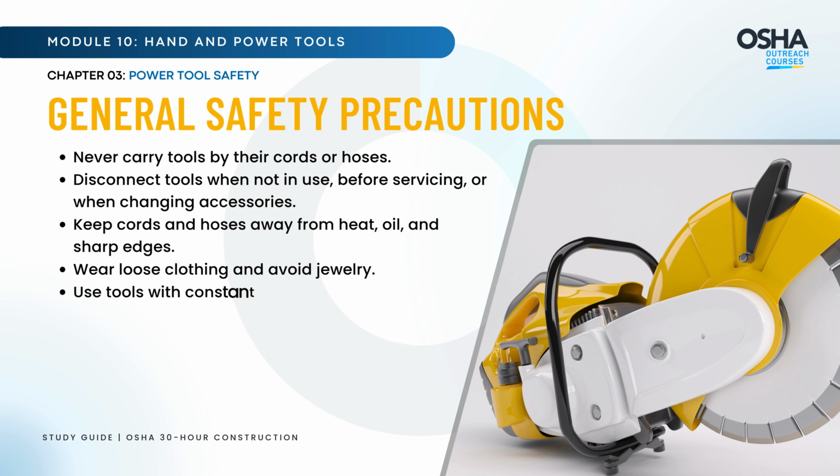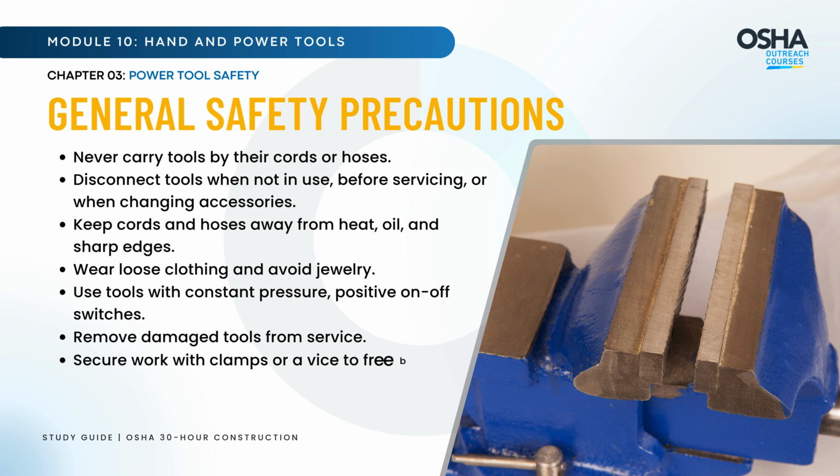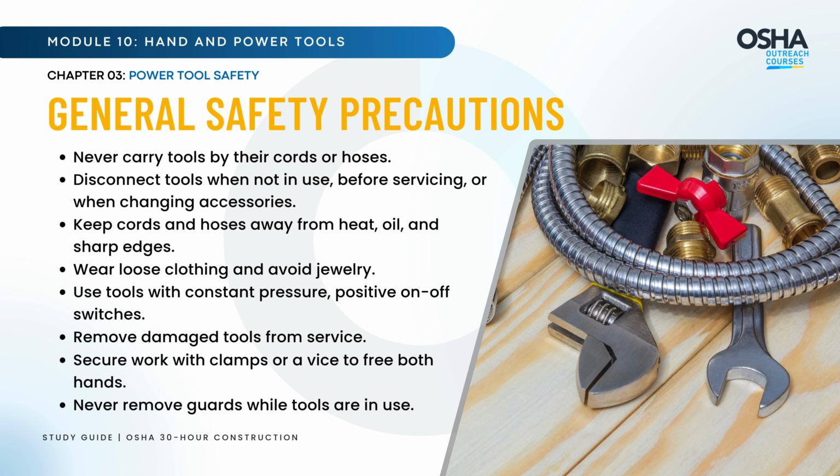Use tools with constant pressure, positive on-off switches. Remove damaged tools from service. Secure work with clamps or a vise to free both hands. Never remove guards while tools are in use.